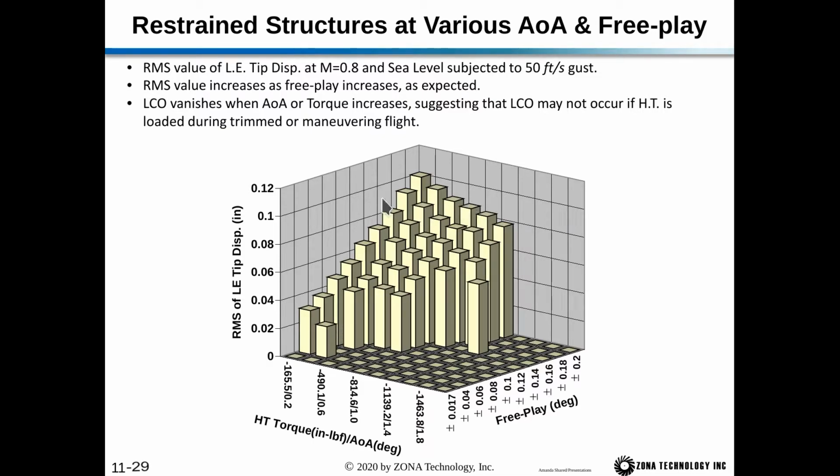increases. Next, the LCO vanishes when the angle of attack or the torque increases, suggesting that the LCO may not occur if the horizontal tail is loaded during trimmed or maneuvering flight. So as our angle of attack increases, the RMS of the response decreases. And when we increase the angle of attack enough, we can actually make the response completely disappear.